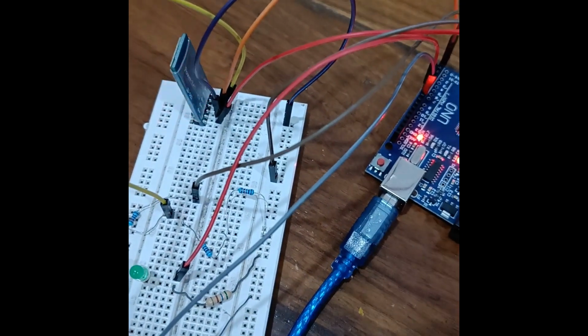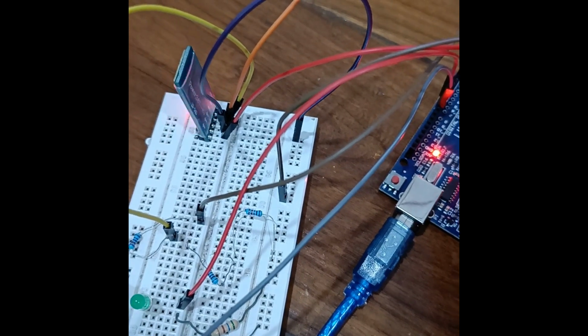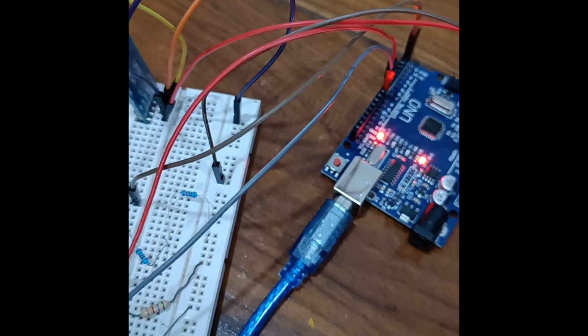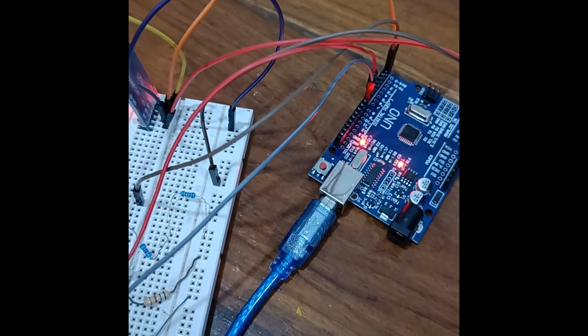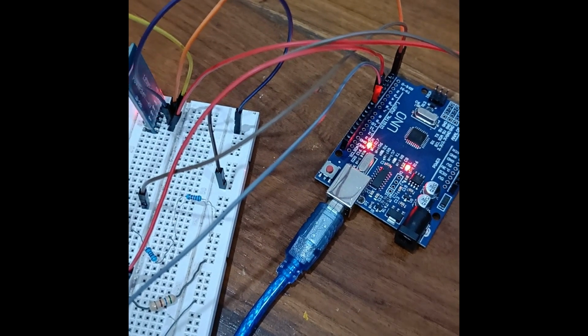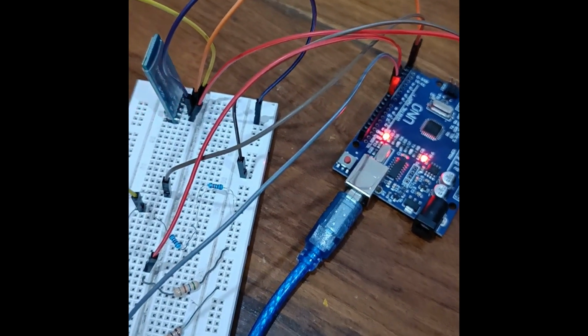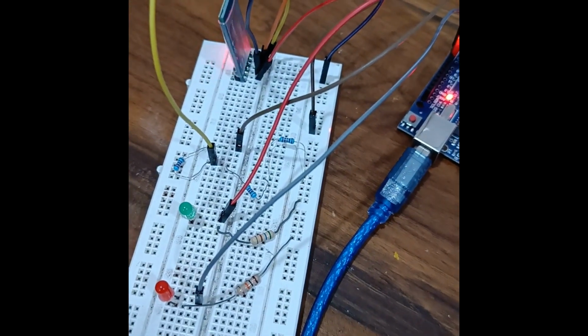But if you take some other port, just like pin number 2 or 3, apart from 0 and 1 on the Arduino board, then you don't need to open the wires from that board, and the code you have to modify. You have to take some header file, and you have to define that those pins are receiver and transmitter. That is a different way of approach. In my case, you have to open the pins when you dump the code, right? So this is the circuit.